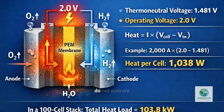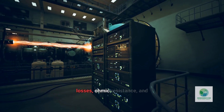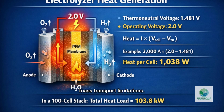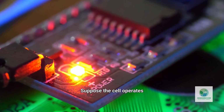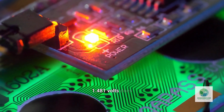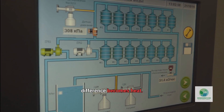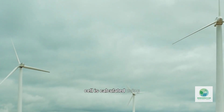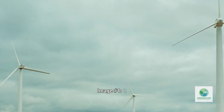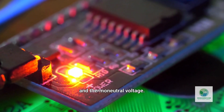But real systems do not operate at 1.481 volts. They operate at higher voltages due to activation losses, ohmic resistance, and mass transport limitations. Suppose the cell operates at 2.0 volts. The difference between 2.0 and 1.481 volts does not go into hydrogen production. That difference becomes heat. The heat generation per cell is calculated using the equation shown on image number 1. Q equals current, multiplied by the difference between operating voltage and thermoneutral voltage.